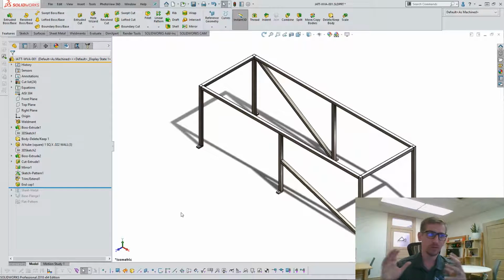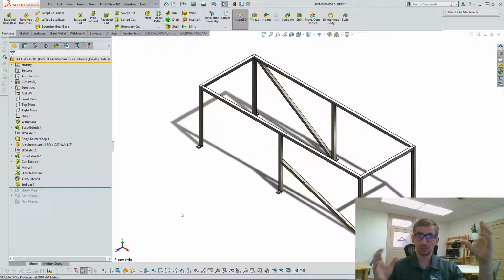let's say in this scenario, we came from a 2D drafting software such as AutoCAD or DraftSight or something like that, and we didn't utilize the weldments function. We just drew each part in AutoCAD, and then we made those as blocks, and with those blocks we put them into a master part file or AutoCAD drawing file and assembled it in there to make sure everything fit. Well, in SOLIDWORKS you could do that, but really you're better off using weldments.